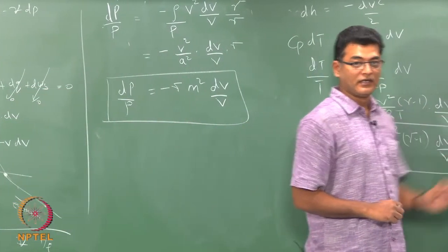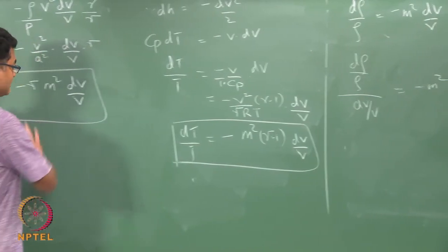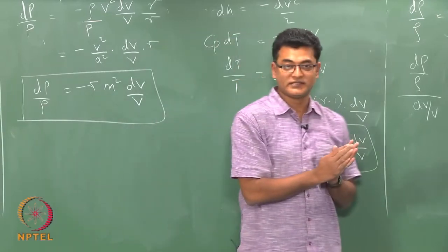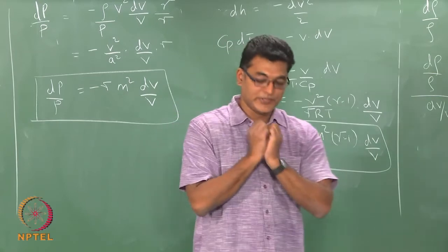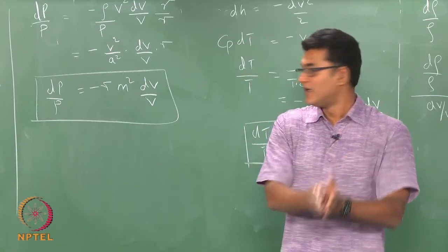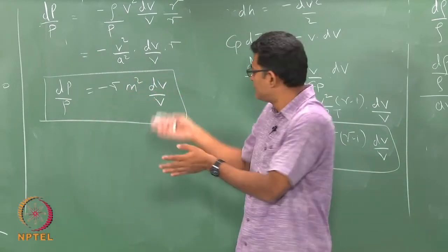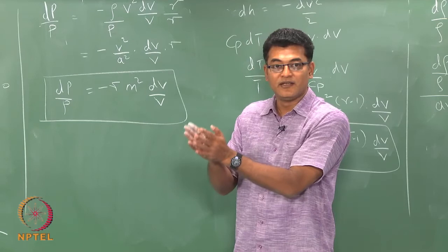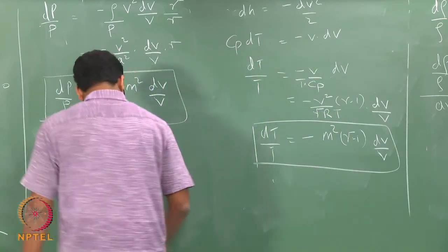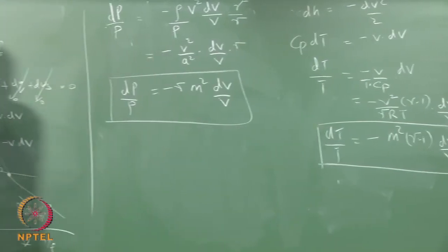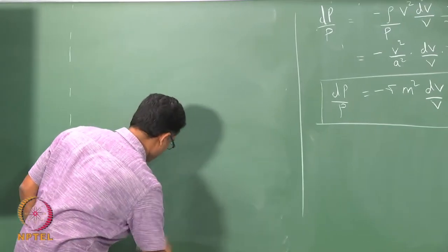Now, we include this along with our area change. So, this process has nothing to do with your area change, but now given the total energy and how we know how to produce a velocity, and now we know how the pressure, temperature and density change due to the fractional change in velocity, we relate that to area change. So, like in the previous class, we will gather these equations and write them down here and try to see what they mean.